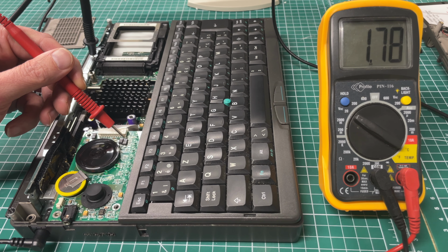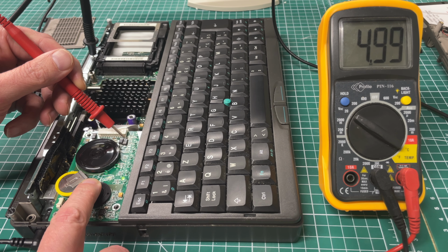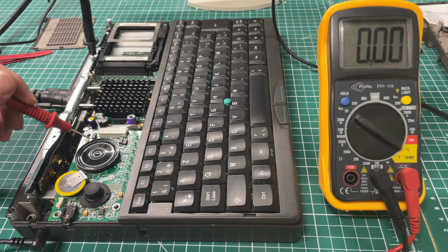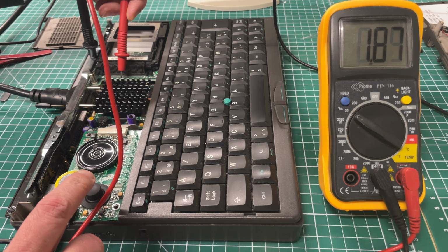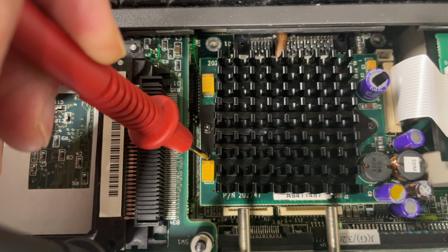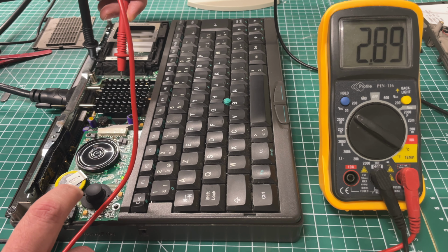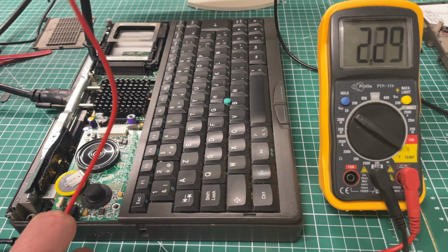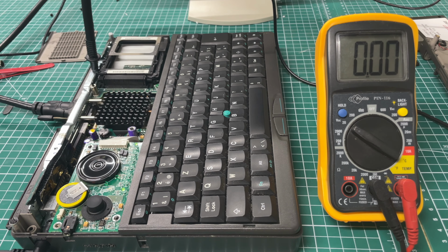So with the machine turned off, it's really fluctuating the voltage here on this cap. So if I try to start it again, it goes up to 5 volts. We hear the machine starting. And then after a couple of seconds, it will probably just shut down like it does here. And again, you see the voltage fluctuating. Now we can also measure the CPU voltage on this cap right here. And normally this should measure 2.9 volts, which is the nominal voltage of the CPU. And we see it going up to 2.9 volt, but it's not able to maintain that voltage. So the machine just shuts down.